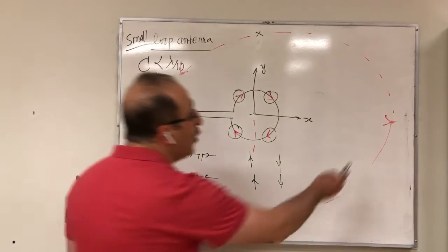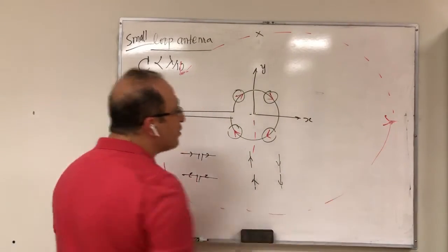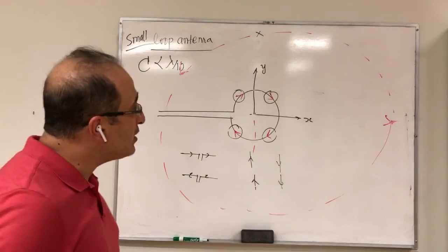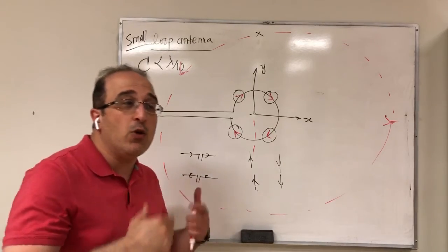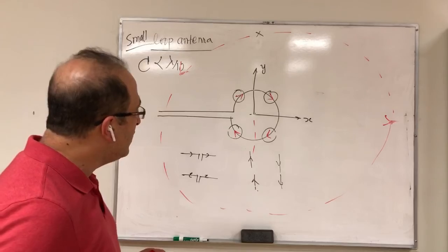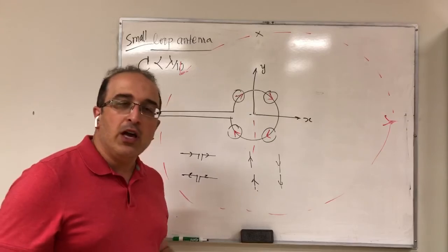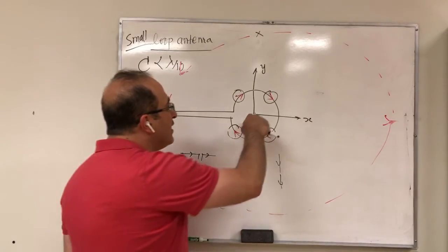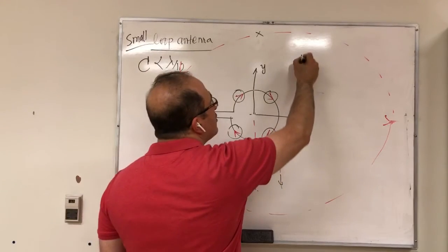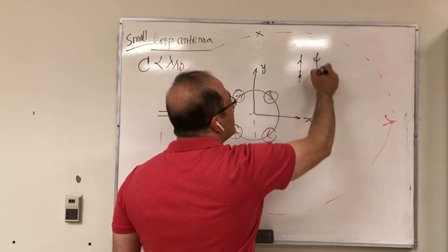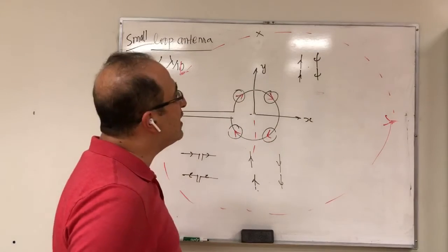But the thing is, when you go around, by the same argument, you can say everywhere around sees the same thing, because all of them see two dipole antennas a little bit separated, so they don't completely cancel the effect of each other. Therefore, you still get something, but you get it equally. Then at this point, you might object that you said on the axis you don't get anything, but on the axis, I still could see two dipole antennas separated a little bit. So why on the axis did you say there is a null?